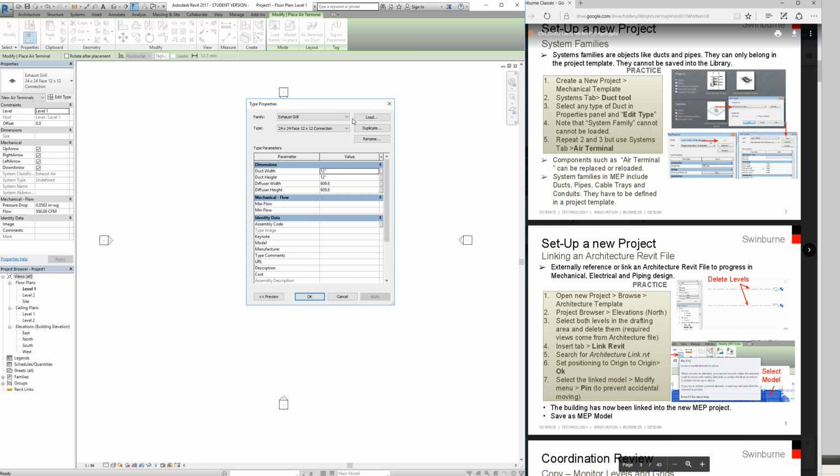Same with piping. You can change the class, the diameter of the pipe, but it's round shape, like similar thing always. While a parametric family or a standard family, you can create in a separate RFA file. So that's just to show the students what is the difference between these two families.